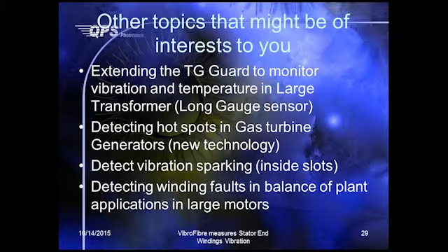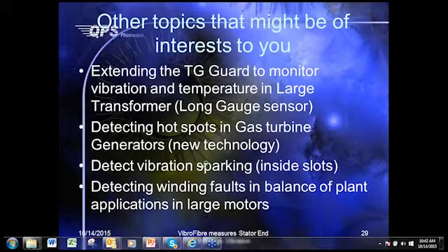Now, one important area that we discover would be to monitor the vibration inside a transformer. The transformer winding can get disturbed when you have a lightning event, when high current surges through the grid and physically moves the coil. However, once the coil has been moved, there is no force to recover it to the original shape. So this introduces an enhanced vibration which we can monitor.